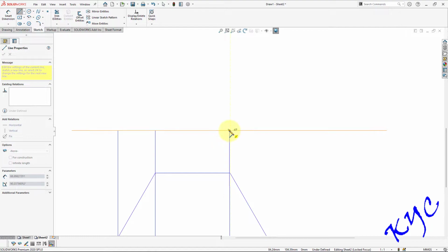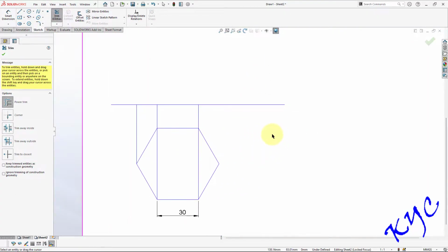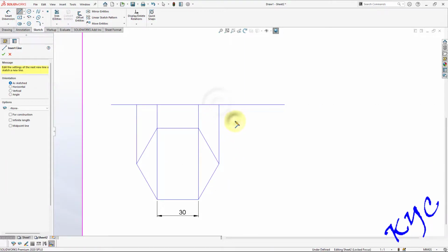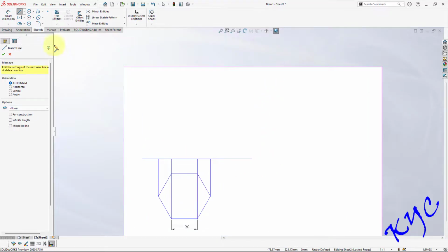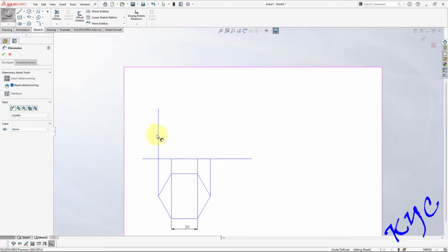Now you go to the front view. I'll draw the front view. Drop projectors towards the XY line. How do I exit from the line tool? Sometimes see here, there are 2 points here. If you connect to the midpoint, it is wrong. Why? Because the projector what you are drawing is not vertical. So give preference to the vertical, right? Right now you can click here. Many students will ask, what we should do suppose if we are not getting this. So draw a vertical line, go to trim, trim it. It's the best way to tackle this problem. Go to line, draw it. Now let us complete the front view now.